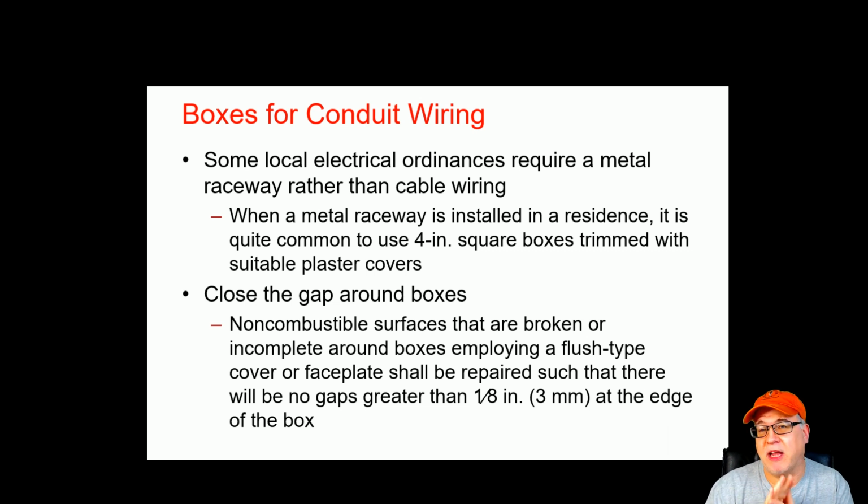You're going to hope that your box is not going to be hidden, okay? But when they cut it in, if they create a gap around it, then you're going to have to do something about that gap. And that's your responsibility, even though the drywaller or gypsum boarder might have done it to you. You have to maintain the integrity of that wall.